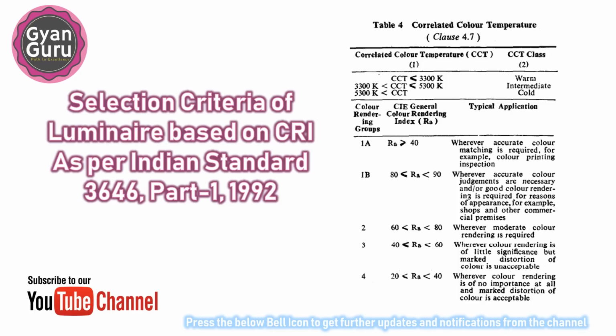For a range above CRI 40 but less than 60, those light fixtures can be used where there is little significance of color rendering but marked distortion is not acceptable. For a range between 60 to 80 CRI, those light fixtures can be used where moderate rendering is required. For a range above 80 CRI, those light fixtures are required in an application where color judgment is necessary, such as in malls, hospitals, server rooms, shops etc., where good rendering is required for reasons of appearance.